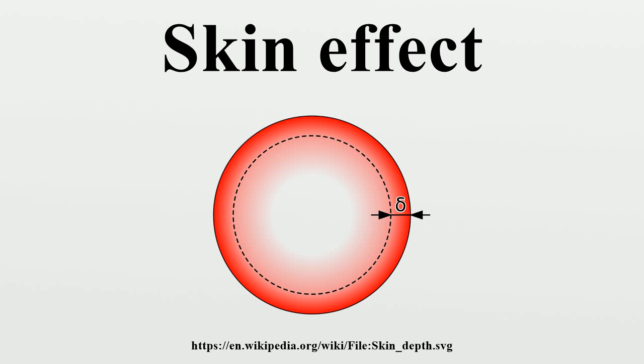Iron rods work well for direct current welding, but it is impossible to use them at frequencies much higher than 60 Hz. At a few kilohertz, the welding rod will glow red hot as current flows through the greatly increased AC resistance resulting from the skin effect, with relatively little power remaining for the arc itself. Only non-magnetic rods can be used for high-frequency welding. At 1 MHz, the skin effect depth in wet soil is about 5.03 meters, in seawater it's about 0.25 meters.